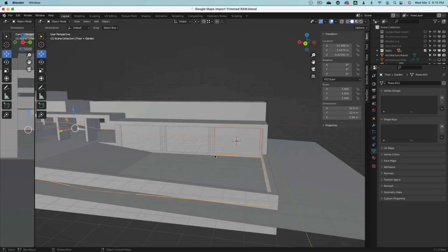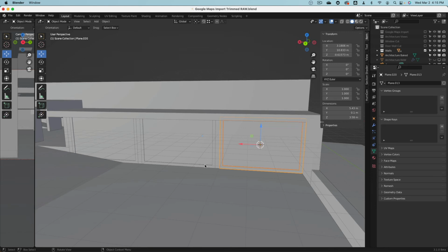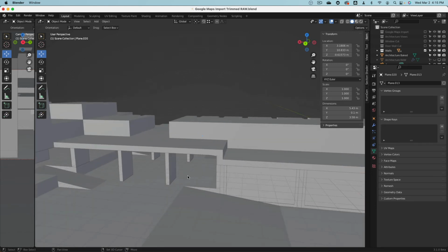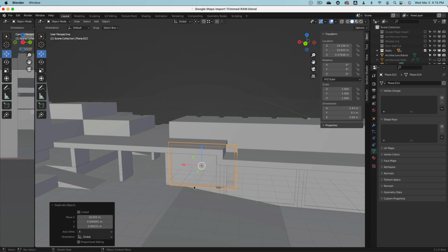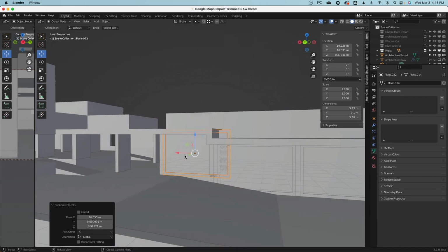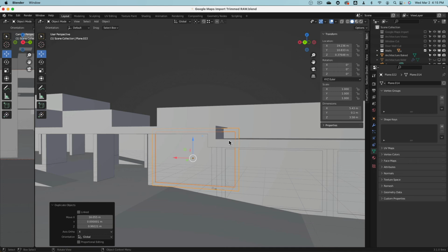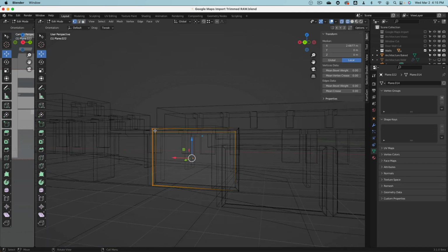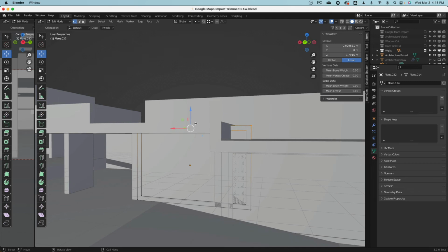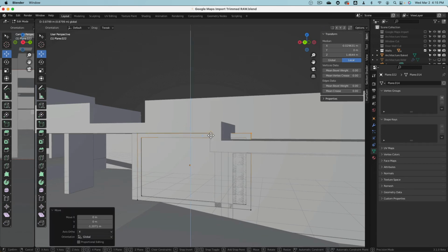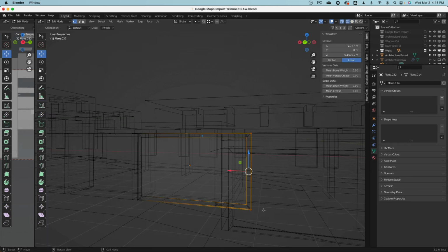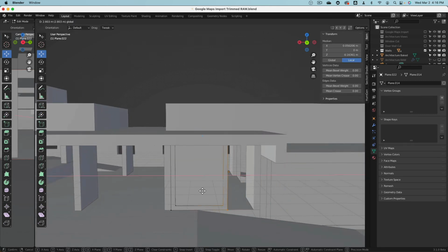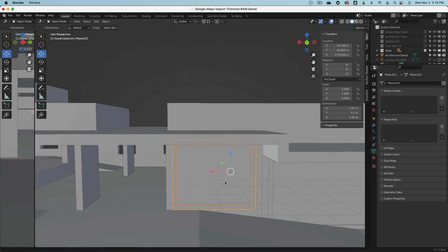Goodie. No, U and U. Sorry, U and U. Shift D, hold control and snap it to there. Then with both objects selected, this is a nice advantage of how you can work in Blender. Tab. We are now working in the geometry of both objects. A, B, select the top and whoop, there we are. Z for wireframe, B, Z for shade, and move this to here, move this to there, tab, done.